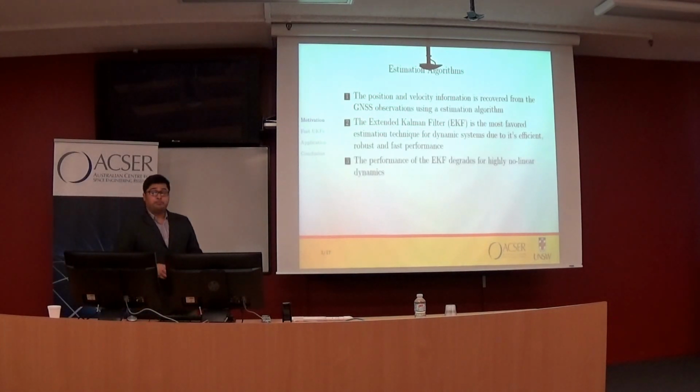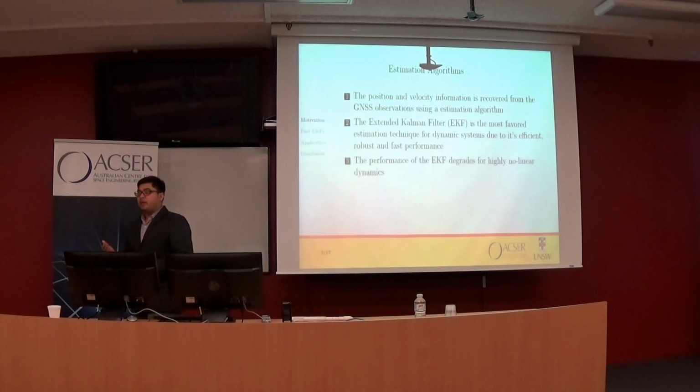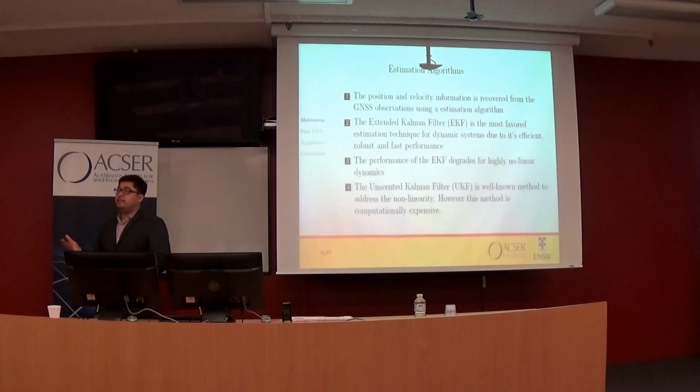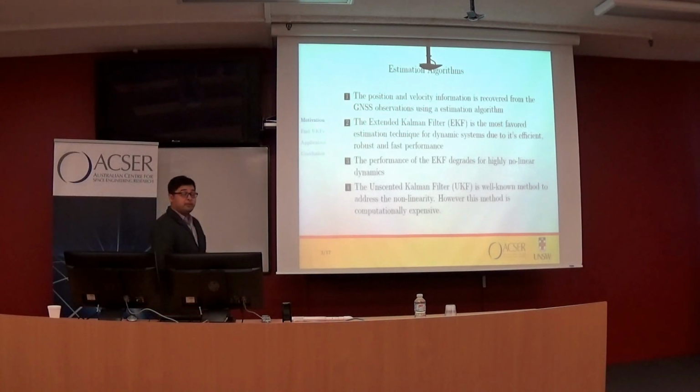But the problem with the EKF is that if the nonlinearity is higher, its performance degrades. And then there's another filter called the Unscented Kalman Filter, which is a well-known method for nonlinear applications. It can handle high nonlinearity and give us better accuracy than the extended Kalman filter. But there's a problem with the Unscented Kalman filter: it is computationally very expensive. It takes a long time to process, so it's hard to implement in real time on board.